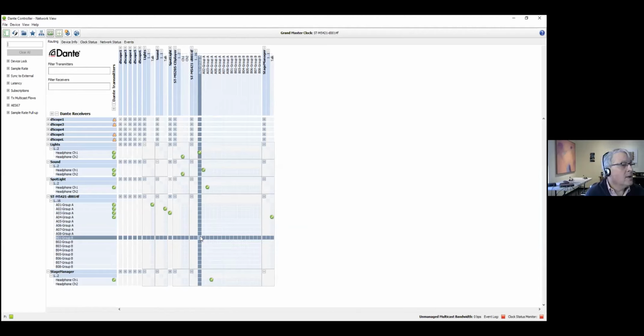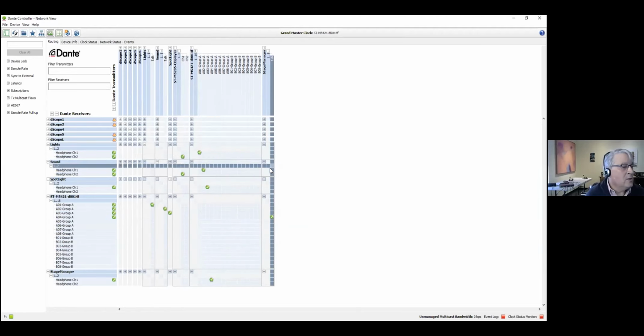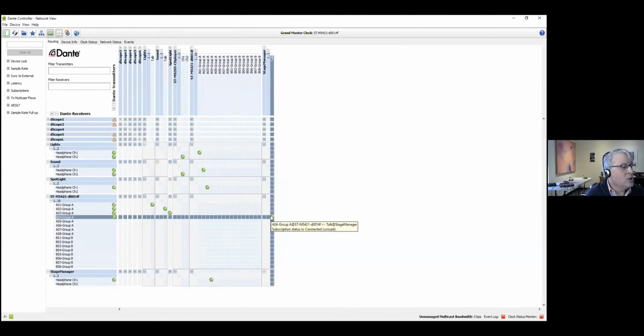Now, the belt pack talk go into inputs on the Dante engine. So basically, for every channel, there's 2 connections, and it's not overwhelming you. It just takes a little practice. But what I've done here is all 4 belt packs can communicate with each other, and 2 of them can also hear 2 of the channels from the CD player.